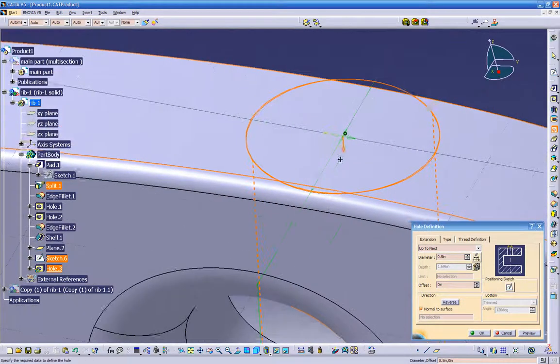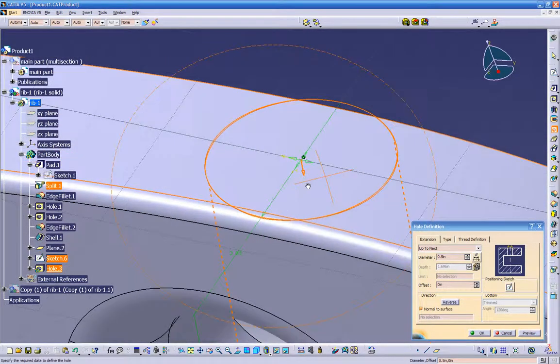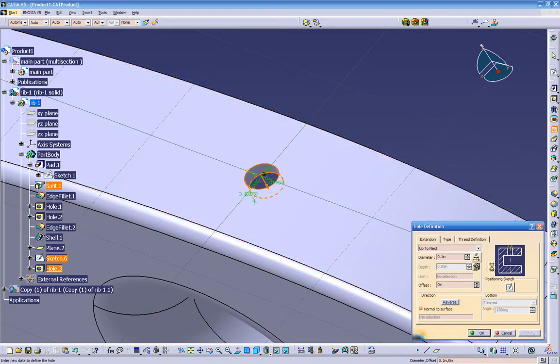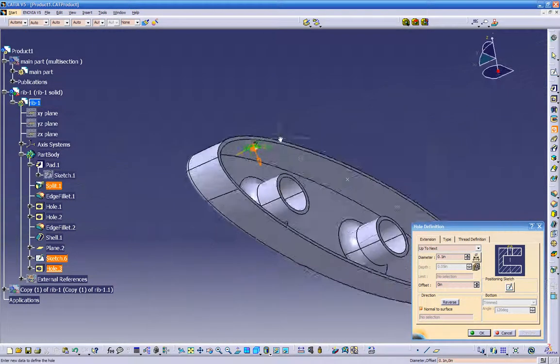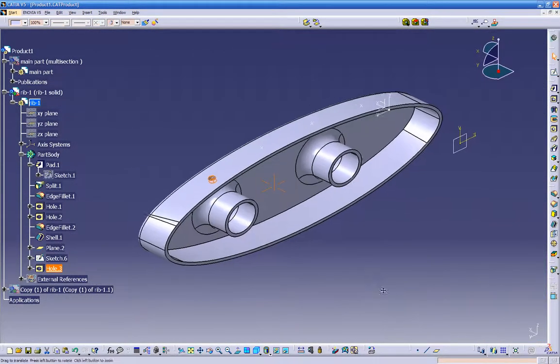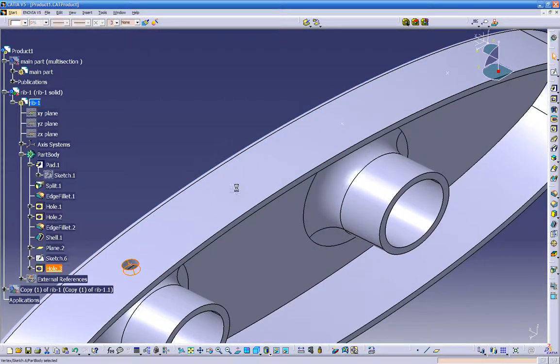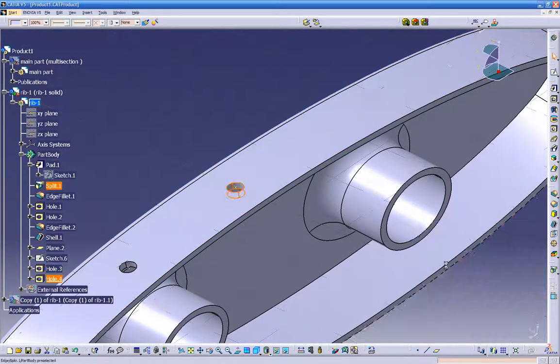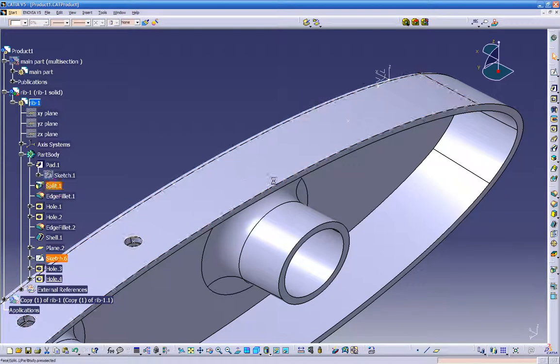And if you see what happened, right now our hole is right in the middle of our point. So we can change this. And let's go up to next. So there's our hole. Click OK. So first select the point, second click on the hole, and third click on the surface. And just click preview, OK, and repeat this option for the rest of the remaining points.